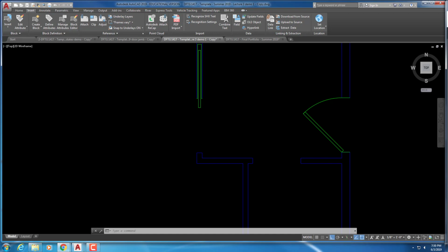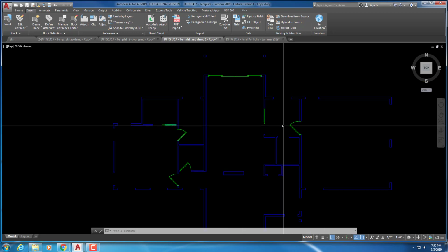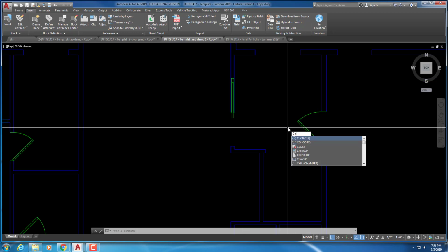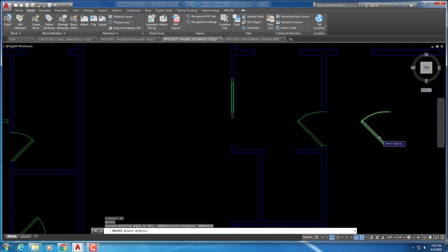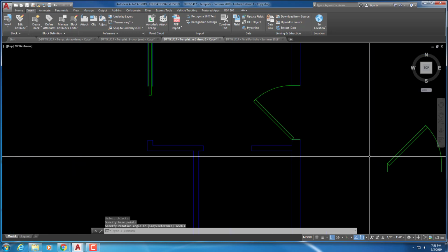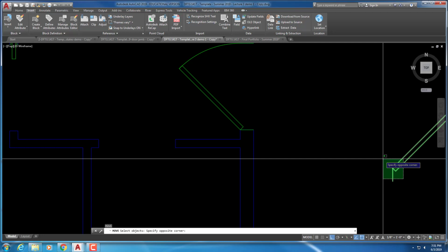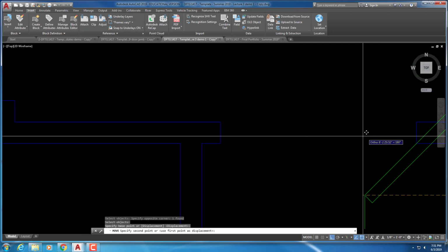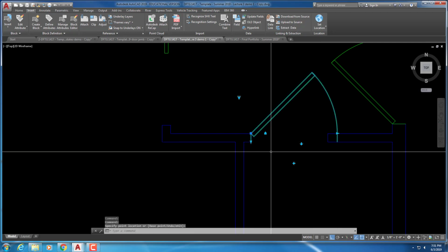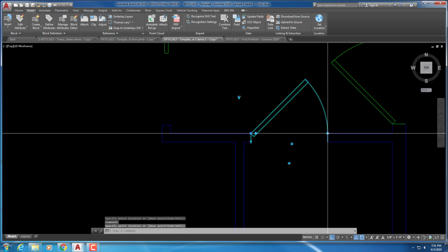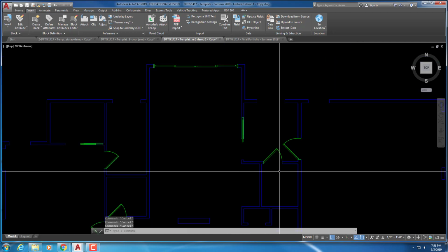The D2, I'm looking at the door schedule, is a 2/8. And that's this door here. And it's opening back that direction. So I'm actually going to copy, and then I'm going to rotate the door. I think it's just a little bit easier. And then I'm going to move that into place. Change the jamb thickness to the width of the wall. Change the door width to the correct size.